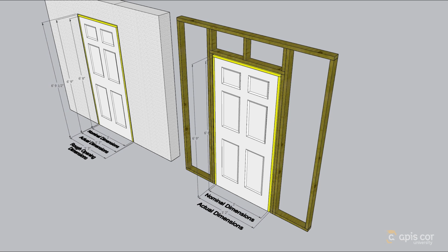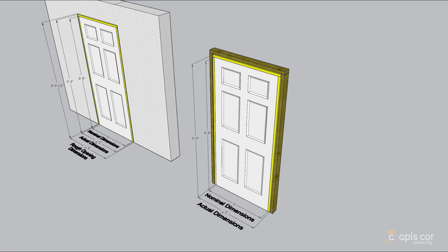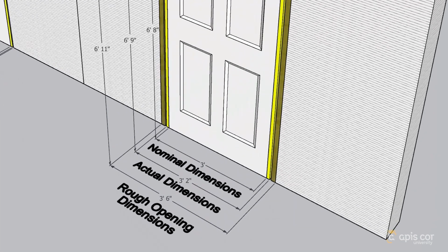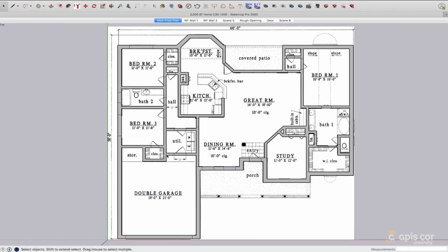If you are using these types of doors, then you will also need to install wood bucks inside of the rough openings, which will be attached to the 3D printed walls and serve as the anchor points for these pre-hung doors. Assuming we will use 2x4 wood studs to frame out the wood bucks, we will need to account for the additional thickness in our rough opening calculation. This will increase our rough opening width from 3 feet 3 inches to 3 feet 6 inches, and our rough opening height from 6 feet 9.5 inches to 6 feet 11 inches.